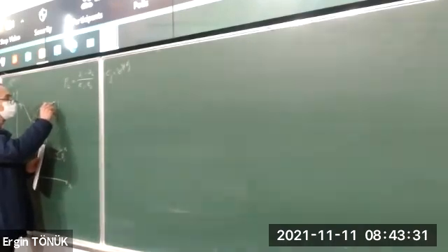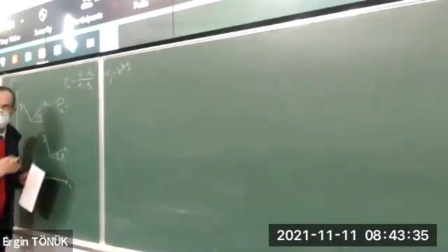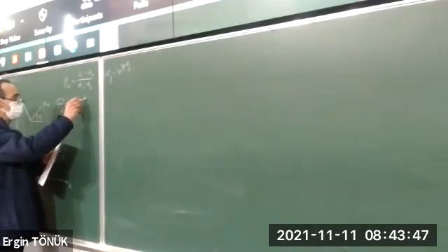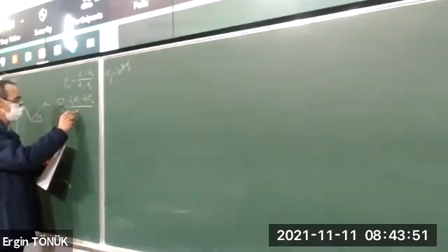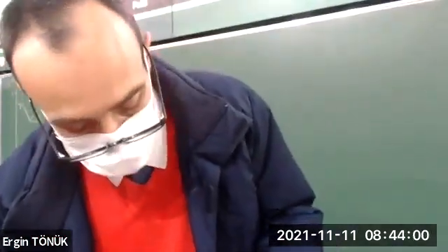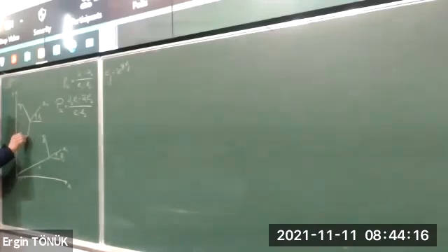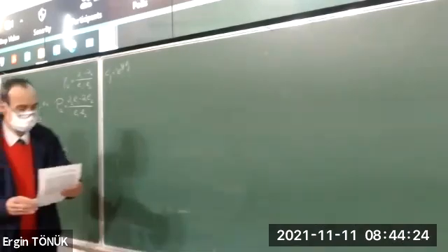Similarly, in the fixed coordinate system, it's a coincident point and it has unique coordinates again. As we derived last time, it was (A2 E1 minus A1 E2) over (E1 minus E2). And actually, the A's were complex numbers representing the coordinates of the origin of the moving coordinate system with respect to the fixed one. So that was A1, that was A2, in complex numbers. Okay. Any questions on this that we have seen last time?